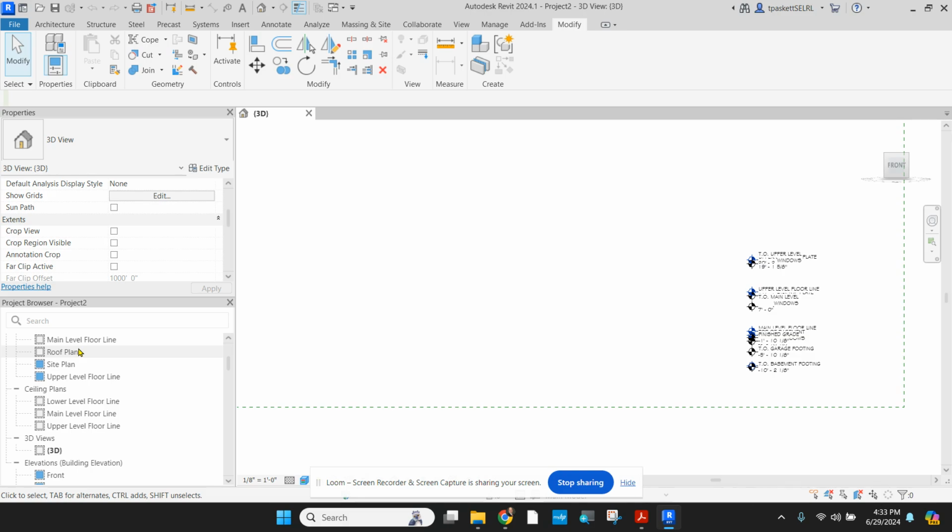But the thing that governs is that from the ground to the topmost part of your house can only be 35 feet. And that has to do with the length of fire truck ladders, which are 70 feet. If we have a 35 foot by 35 foot triangle, then the hypotenuse is the 70 foot angle we're looking at, to make sure that we're not causing problems for the firefighters. They prefer, if we are fighting a fire, to do it from the roof down. So if they can get up on the roof, they prefer that, but they do worry about the length of that ladder being able to reach the top of the roof. If you're 35 feet high, then you have to be a certain distance from the house in order for that to happen, and that might be too close. So anyway, trig's important. If you haven't taken it, learn it.